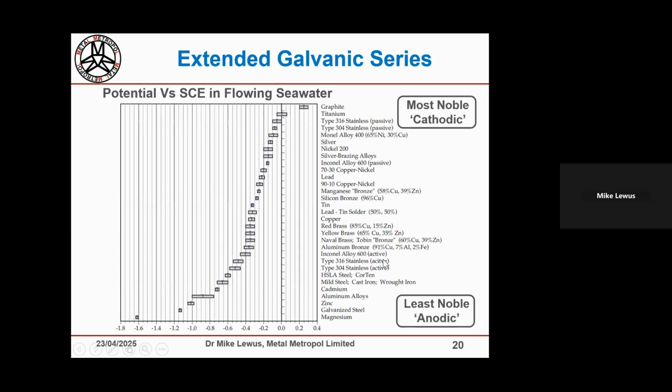I think I made the connection between the standard electropotential series and this one. In effect it is the same, but instead of putting the metal in solutions of its own salts, we're obviously putting it directly in seawater. This extended galvanic series looks at the potentials that develop when all these materials are put in flowing seawater, which immediately tells you there's a lot of oxygen about, so they'll very readily